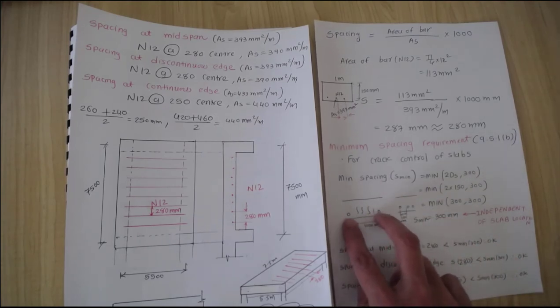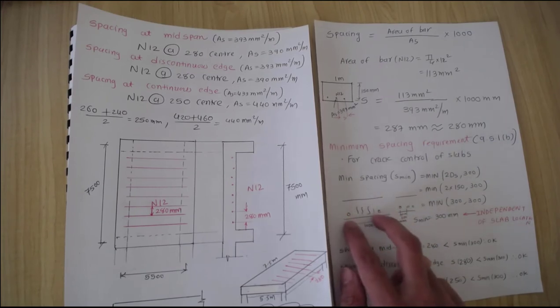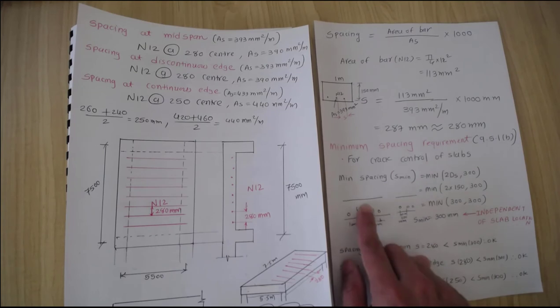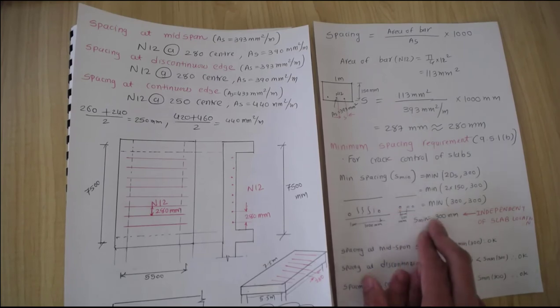So if you have these two reinforcements far apart, if you are sitting too far, then your crack will travel through this reinforcement. It's like a soldier in your army. You don't want to put them on the border, let's say this is the line of control, you don't want to put your soldiers very far apart, or your enemy will get in. Let's say crack is our enemy, so you want to stop this enemy, the crack. If you want to stop your enemy coming into the concrete, you would put these soldiers close to each other, and the standards say that you put your soldiers, meaning the reinforcement, close to each other, which is a minimum of 300 millimeters.